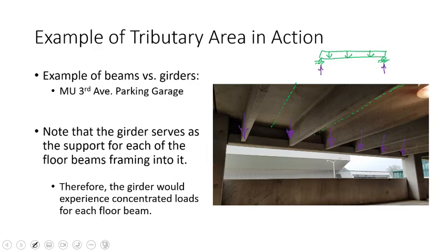Yes. So you're saying reaction A on the end of the beam, going to the outside, would be the same as the downward force, and you had it for every one of them, the whole length of the field? Yes. Yeah, because what's going on is this. Here's the beam, right? And there's the reaction force, and there's the spandrel girder that it's sitting on. So the spandrel girder is seeing that downward effect. Does that make sense? That's a good question.